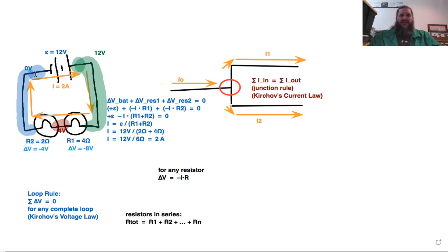So I would recommend setting it up in this sort of way. When you're analyzing any circuit, see if you can figure out what the current is through each path, and also map out what's the voltage in each region, each zone. And drawing it out, like highlighting regions of the wire, it's not really an official formal notation. It's just what I find useful for visualizing where the voltages are.